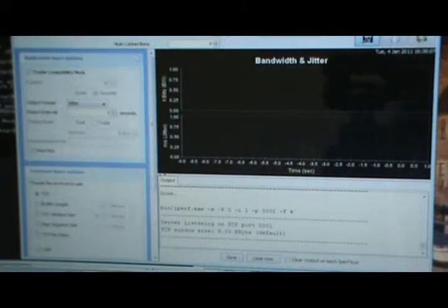To show Wi-Fi operation, I'm using the iPerf utility built for the ARM processor on the client side. To run iPerf, you need one laptop connected to the access point via Ethernet port that acts as a server. We assume that you have iPerf or the JPerf graphical utility installed on this laptop. Also make sure you know the IP address of the server. The Y2Y card connected to the Beagle board acts as a client.